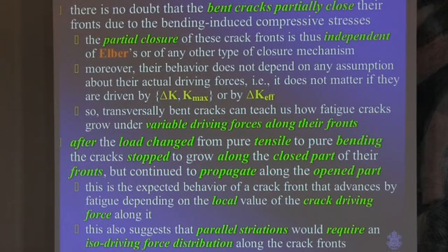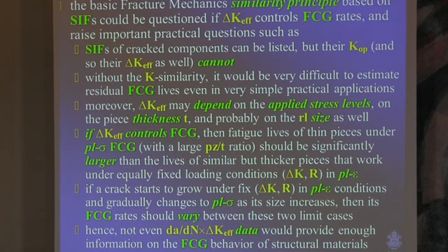No doubt, part of the crack front is closed. No doubt the open part can propagate. So there is no way I can claim that if I pick one point of the crack front, it is not going to grow. However, we decided to do an even simpler test in order to verify if delta K effective was indeed the fatigue crack driving force.